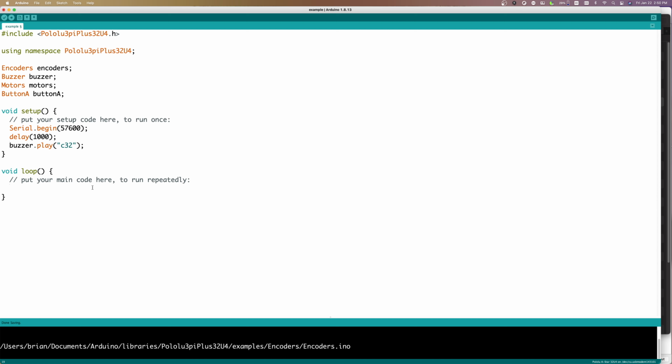And for this very first deployment, we're going to keep things super simple. I'm not even going to bring the encoders in just yet. I just want to put some code in so that we can see the motors work. But to make it so the robot doesn't run away endlessly, I'm going to make it so that the motors will run if we press button A.